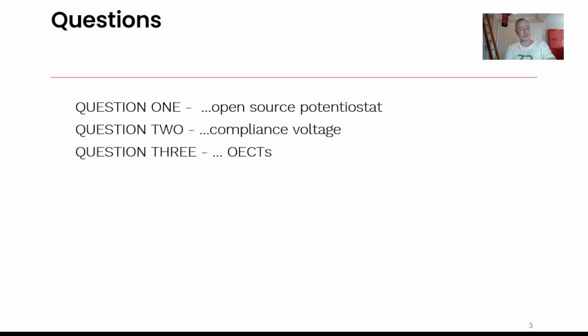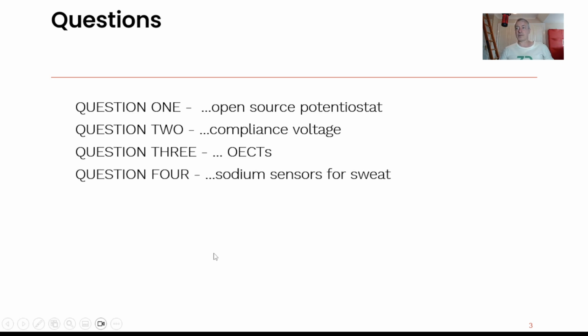If you're using a semiconductor as your material between the drain and source, then I can understand why you would be using semiconductor fabrication. But when you're doing OECTs, I would suggest that you should be using screen printed electrodes. That's my opinion, and I'll be giving you a sense of how I think that can be done.